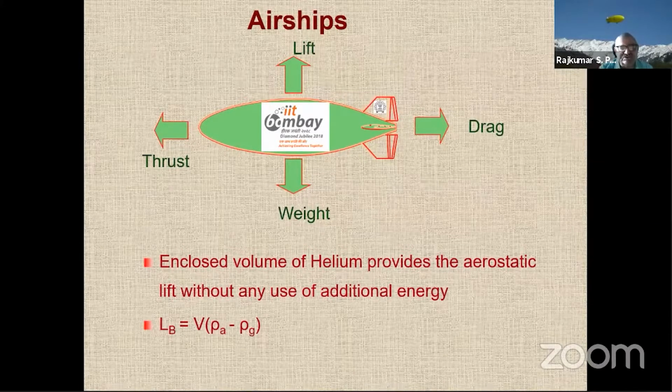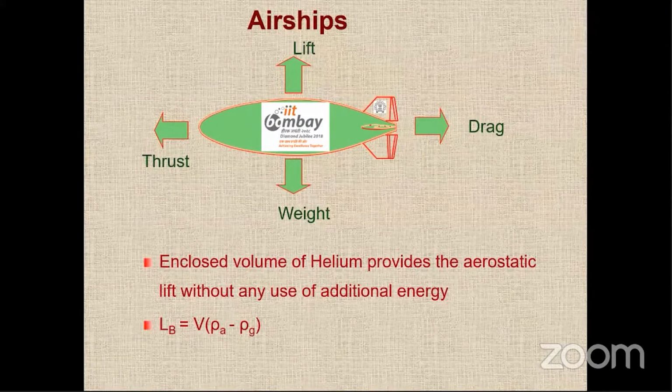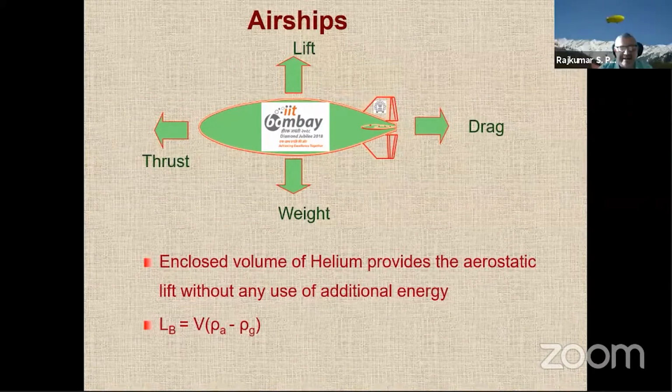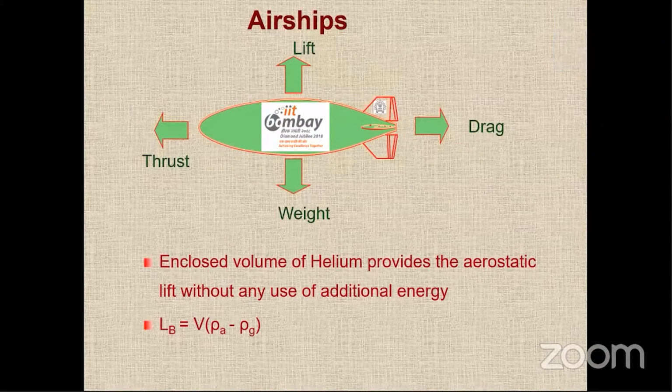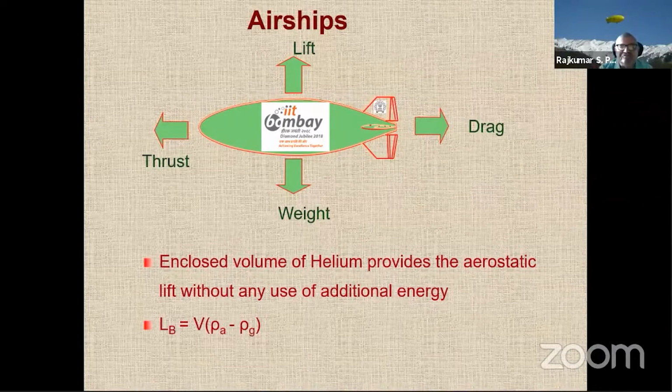So which are the two forces which are natural? Can someone tell me? So weight and drag, right, are natural forces. Lift and thrust are to be created by us. In the case of airships, we don't even have to worry about lift because it gets created due to the buoyancy of the gas filled inside the envelope. So even lift becomes a natural force, and this natural force is a function of the enclosed volume of the envelope and also on the buoyancy of the gas inside.